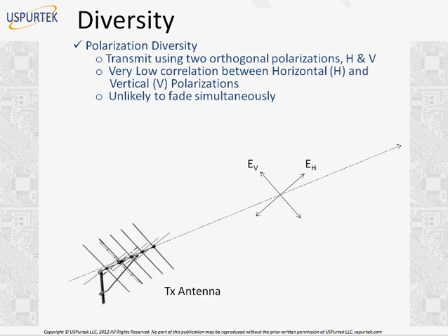Well, there's a question: is there correlation between diversity and impedance? Well, these are two independent parameters. When you say impedance, you define the feed input impedance of an antenna. When it's diversity, we are talking about multiple antennas, and each antenna will have its own impedance. If they are the same types of antennas, they will have the same input impedance for each, and they have independent feeds.